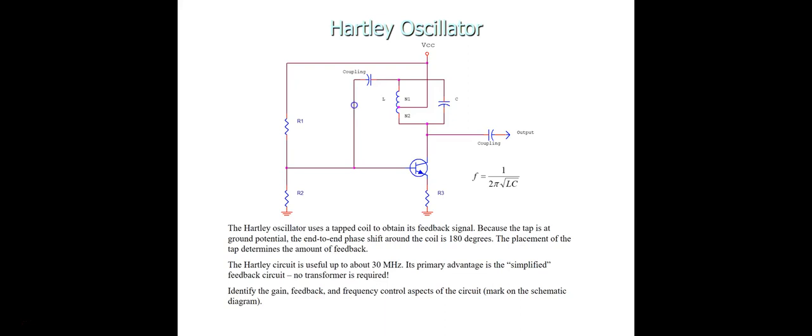So this can be determined by seeing the value of the capacitor. The value of the capacitor here will be around 0.1 microfarad, which is very low, and which has a very low reactance. It therefore appears as a short to AC signals.